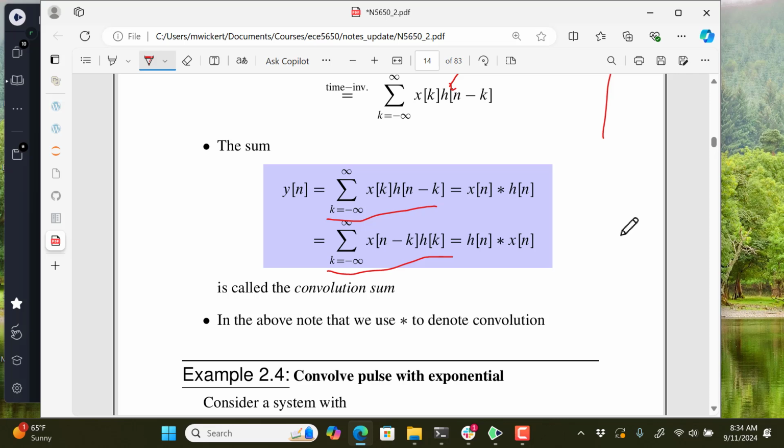You have a circuit that you put together with inductors, capacitors, resistors. You claim this is an input point and this is an output point. If you were going to mathematically analyze the input to the output, you would, through linear constant coefficient differential equation theory, develop a differential equation model to go from input to output. In the discrete time domain, we end up with a difference equation model. Same exact idea, though, linear constant coefficient difference equation.